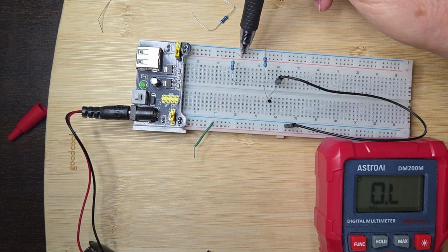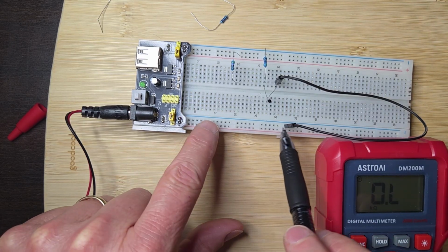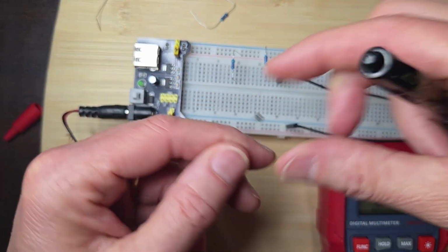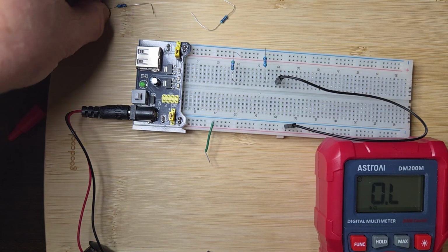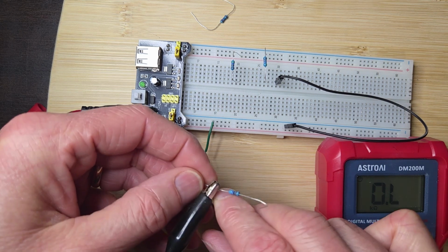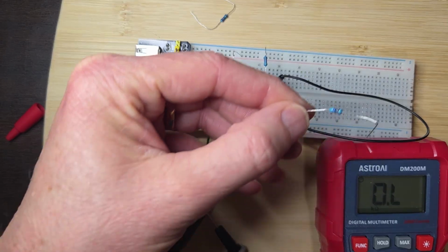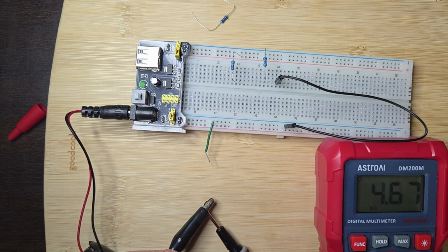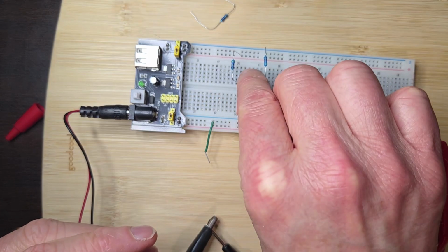You can see that. And then here's my negative rail, and I've got a little wire here just where I can measure things. And this is the thermistor I was showing you right there. But we're going to set it aside for now and just measure. So this guy right here, I'm just going to measure this resistor. Okay, that's 4.7-ish k ohms.